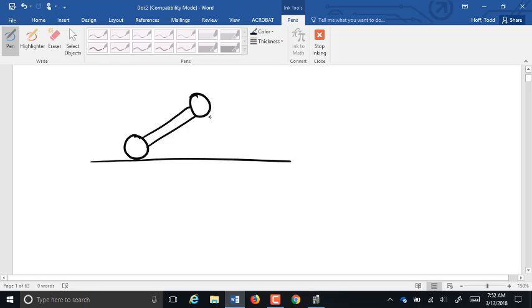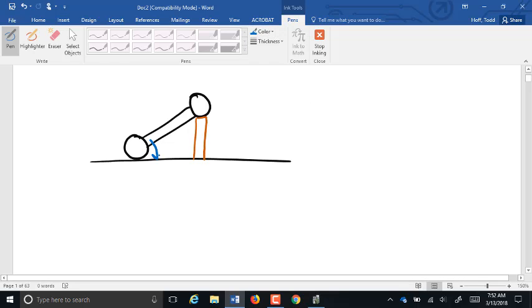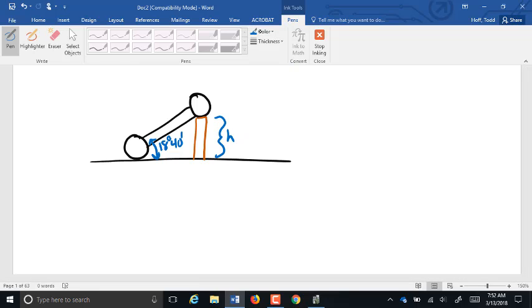So let's say the angle we need here is 18 degrees, 40 minutes. We need to know what height we need here. We're going to call that H. And let's say this is a 10-inch sine bar.